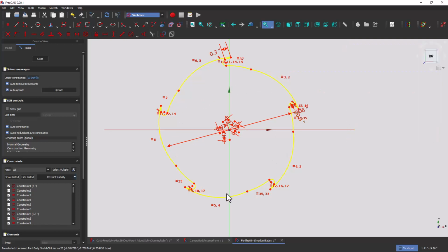It's held in accurately to everything that we've done. If you roll back a few minutes toward the point where I started having the wire is not closed error, if you look at the screen, you're going to see that there were some constraints on a few of these vertices here. And from 3 miles out, they look like that they are coincident. But if you go in really closely, you'll find out. And when I say closely, I mean you're going in with a microscope. You have to go way, way down in there to find out that these are missing each other.